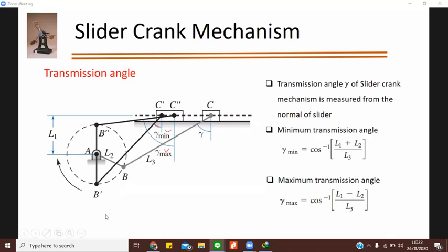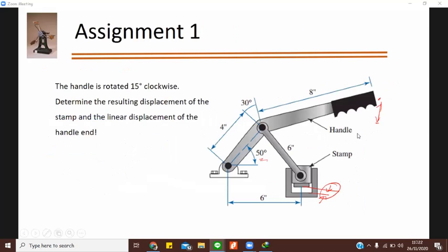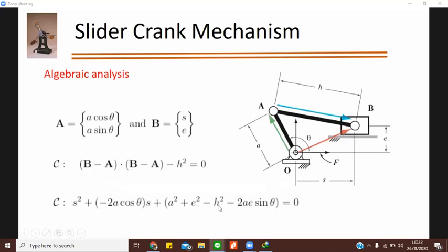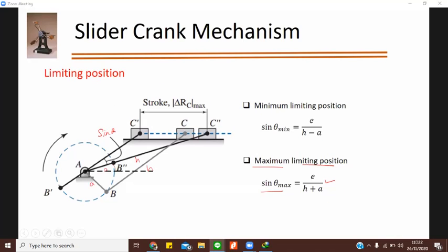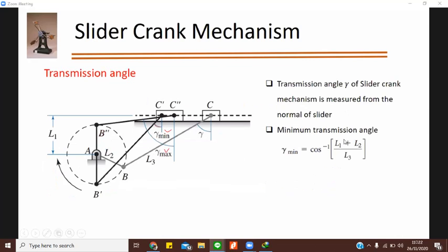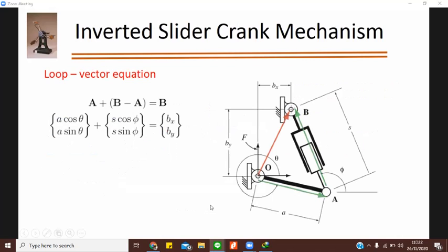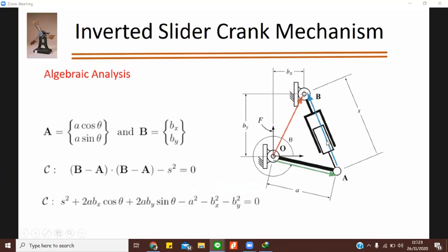This S is the change of slider position from origin, and you had a coupler length H there. But in this example, you don't have a coupler length H in the equation, because the coupler and fourth link are in the same place here itself.